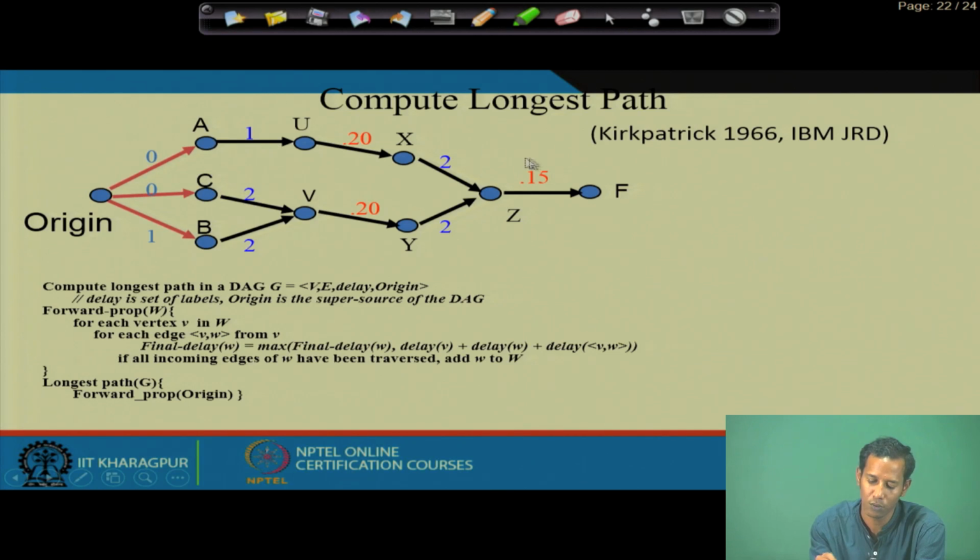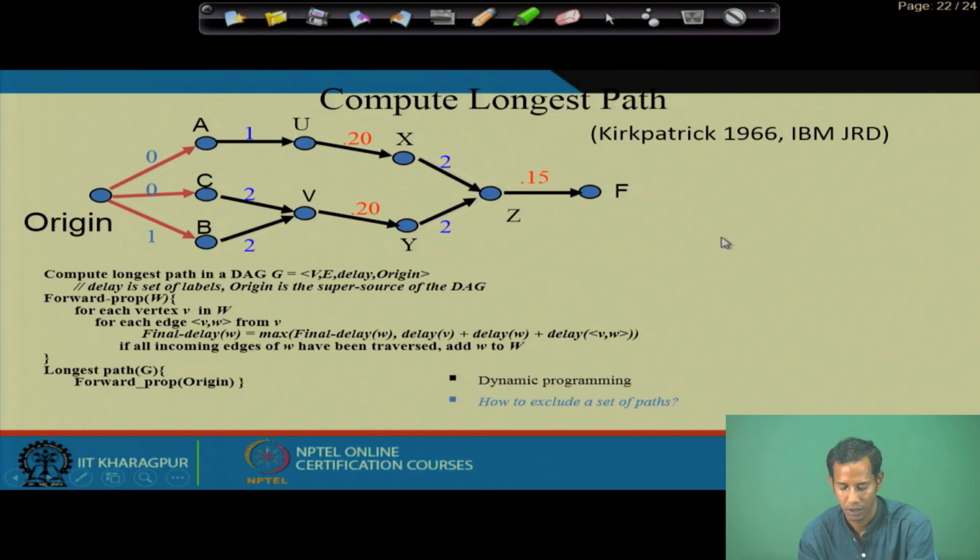So you have developed this graph from the particular circuit. Now you write an algorithm that calculates, for each of these paths, which one is the maximum longest path from the particular source to the end, which is the point F, and it gives you the critical path of your circuit. Okay. Now here there are actually 1 path, 2 paths and 3 paths.